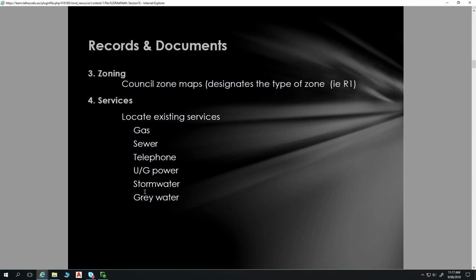Possibly a better way to approach such a thing is to have a tank that serves as the sump, and then you have some overflow feature from that. If your pump fails, well then your overflow is going to be a minimised impact, and that way you get some time to see, okay, that tank filled up in the last rainfall event and it's not clearing out. Is there an issue with our pump? Anyhow, so the same with the sewers as well.